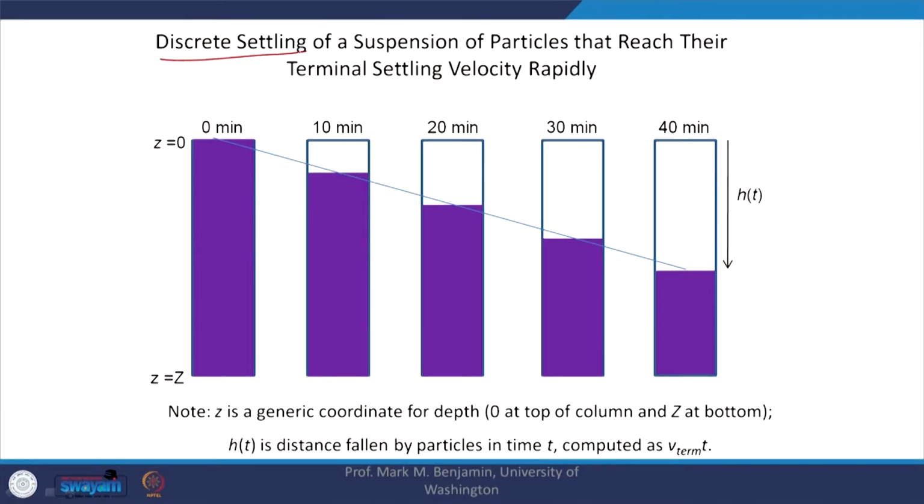And then we looked at how to understand the system and try to design it. And we looked at some data and looked at one example. In that context, let's clear up some aspects or discuss them. So here we have discrete settling of particles, right, where, let's say, gravity minus buoyancy equals the drag force, right? So the particle has reached its terminal settling velocity.